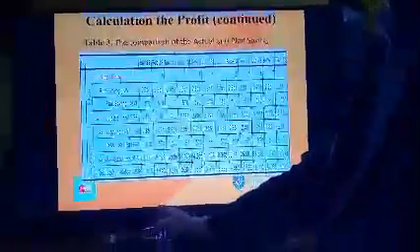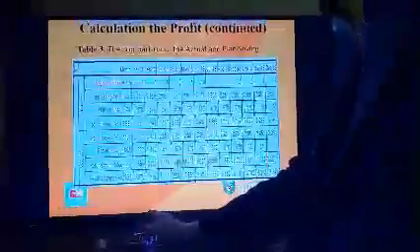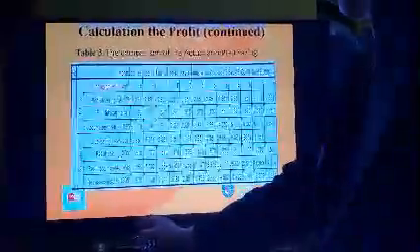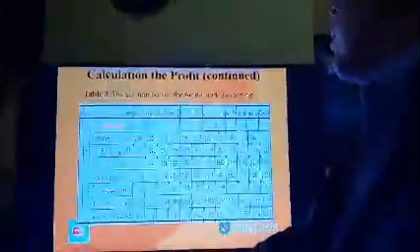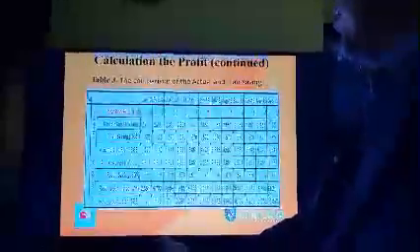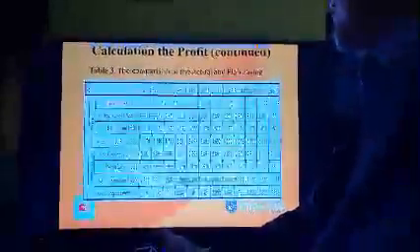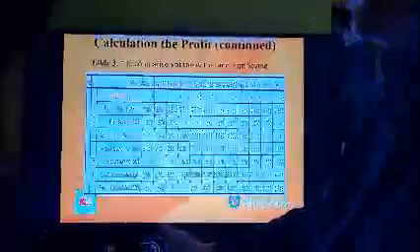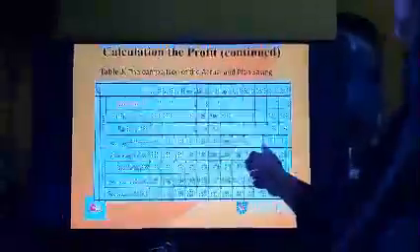So this is the last one. This is the reduction cost of the insulation heat of molding machine. So we already implement it for the 5 machine that's running. We can save 2,851 kilowatt per hour. So that will be accumulate in the Singapore dollar become the 6,843 Singapore dollar.